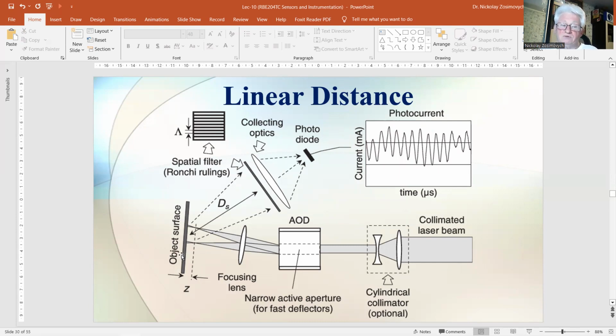If there is not enough space to mount the sensor at the measurement location, the light can be transported to and from the proper position using optical fiber. Since reflectance depends on the reflectivity of the object, operation is restricted to environments with similar objects.